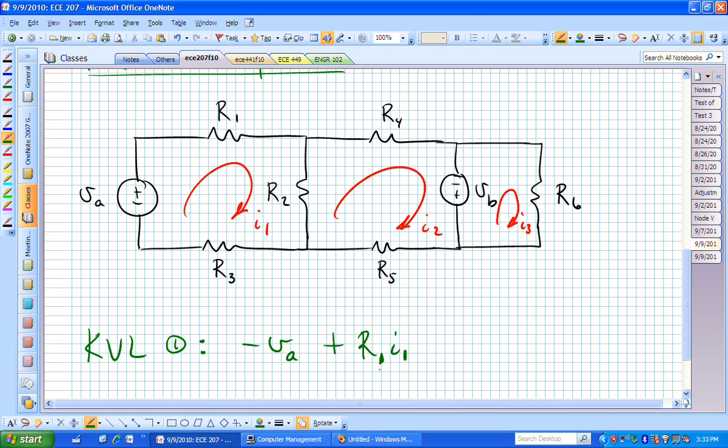Then we're coming vertically down through R sub 2, and Ohm's law says we need to have the resistor R sub 2 times the current going down from top to bottom. What we've identified with our mesh currents is there are two mesh currents involved in that current going down. I1 is going down, helping the current going down.